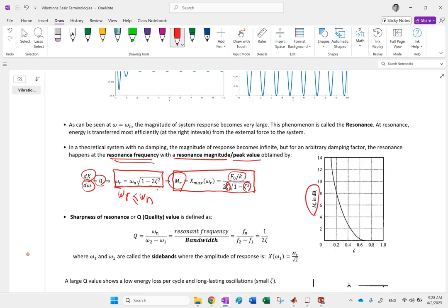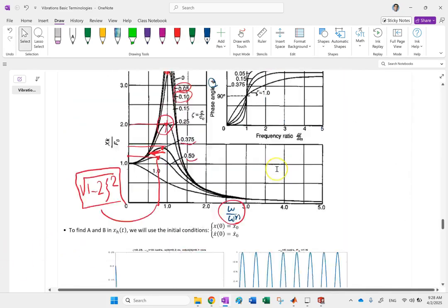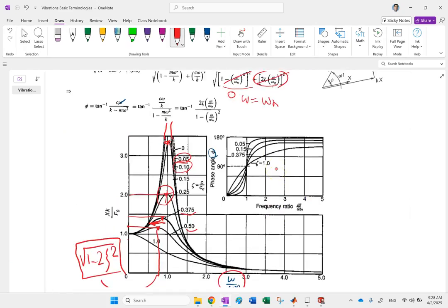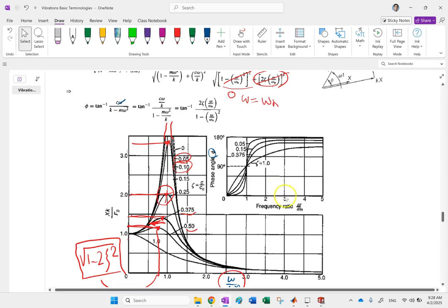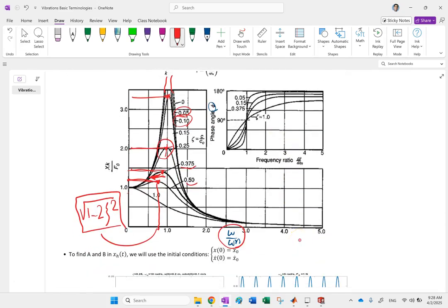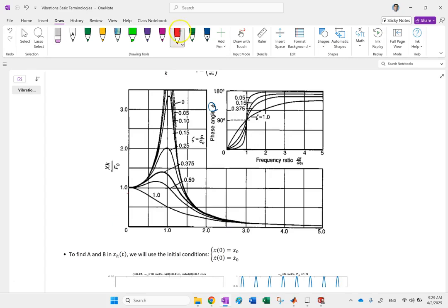And you see that, of course, it is dropping. As zeta gets bigger, M is going to go down. So more damping in the system means smaller resonances, and you clearly can see that, right? Look, you see the height of these resonance values drops as zeta gets bigger, and their omega is further shifting to the left. So this is the X plot. Now you see that there is no maximum in the X plot if zeta passes some number, right? You see for zeta of 1, there is no peak.